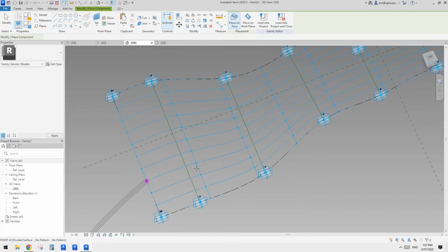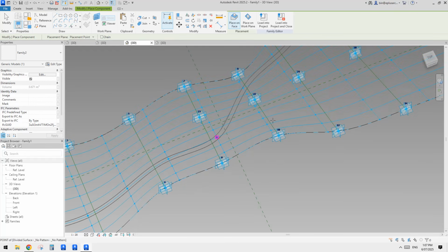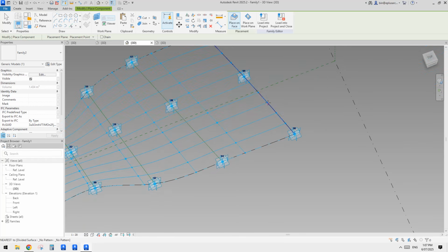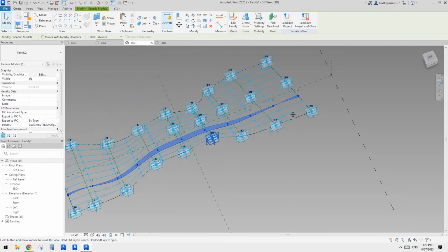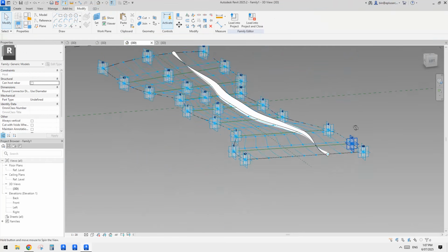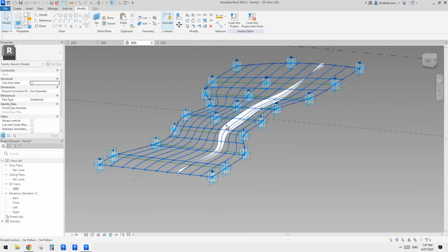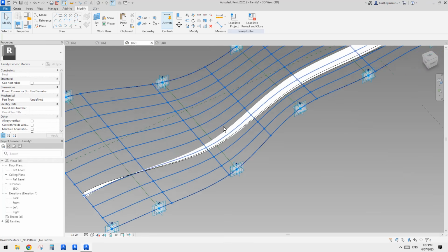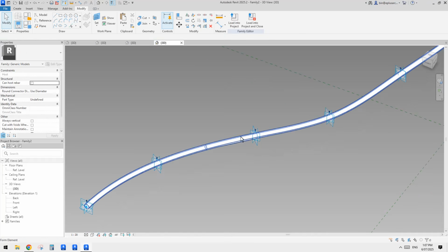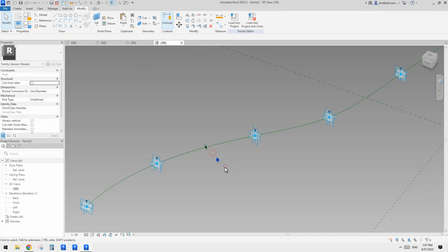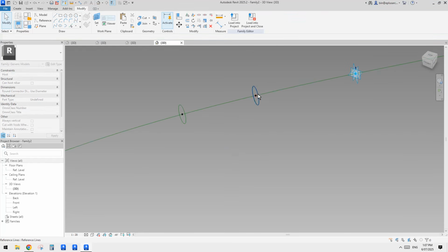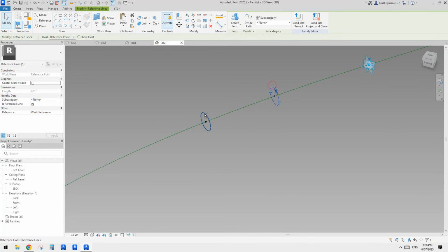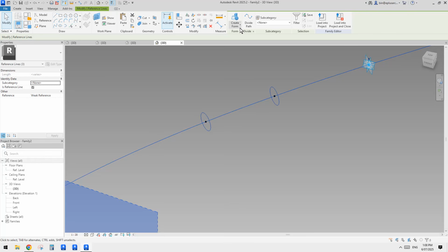So from 1 2 3 4 5 6 7 8 9 10, and the last one here. Okay, see, this is why. It will change the size for some reason. So now we go back, delete this, select this, Ctrl C, copy, pick the point, pick new holes, place back onto this reference line, create a form, use 2 profiles plus this spline through point as the path, create a form.